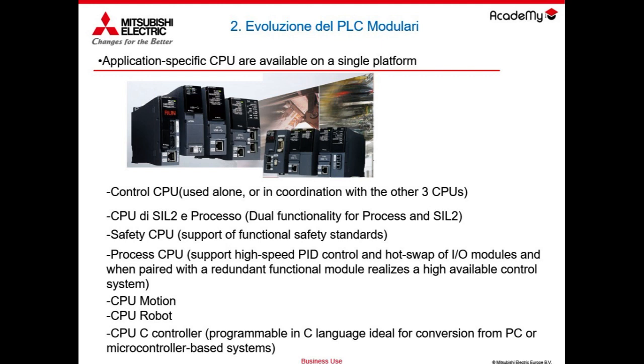So you have a safety CPU, according to the recognized international safety standards, SIL 3 PLe. The safety CPU allows the connection of safety devices such as emergency stops, door switches, and other devices through an industrial Ethernet-based network, CC-Link IE TSN, the latest arrival, without the need for a dedicated separate network. So we will also talk about safety over Ethernet.